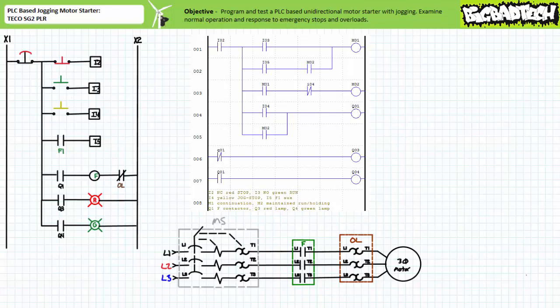If you, however, slow down and walk through this program line by line as would a PLC during several scans, you'll note the reason behind its construction. Virtual relay M1 is merely the means of continuing rung 1 beyond the permissible limit of 3 contact entries allowed for this particular manufacturer. Virtual relay M2 in turn dictates whether the maintained run state has been actively asserted. The holding circuit in rung 2 is established if and only if the F contactor actually closes and the maintained run state has been asserted.